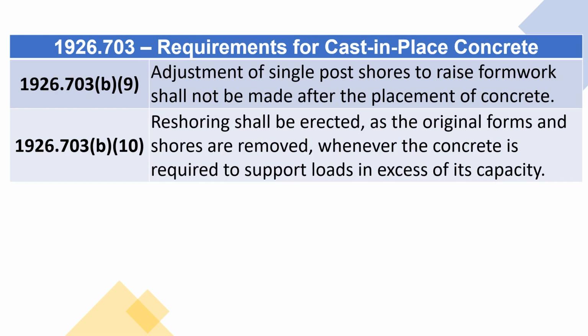1926.703(b)(9) Adjustment of single post shores to raise formwork shall not be made after the placement of concrete. 1926.703(b)(10) Reshoring shall be erected, as the original forms and shores are removed, whenever the concrete is required to support loads in excess of its capacity.